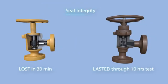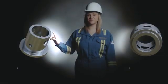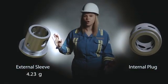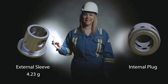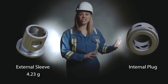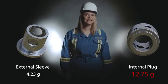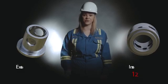The external sleeve's seat feature was outside of the cage, away from the high-velocity turbulent fluid zone, so it lasted throughout the 10-hour test. This valve's material loss was only 4.23 grams. In stark contrast, the internal plug design lost an astounding 12.75 grams. That's more than 3 times the material.